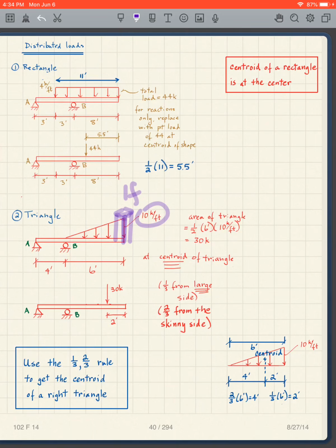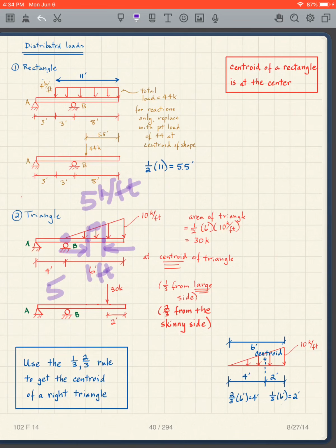I mean, there are some issues with the way I've drawn it, but no matter. I think you understand the way this picture works. I'm at 0 here. In the middle, I'm at what? I'm at 5 kips per foot. So if I take a section of 1 foot here, in other words, if this distance here is 1 foot, then I have 5 kips in that 1 foot, because in that region it's 5 kips per foot.